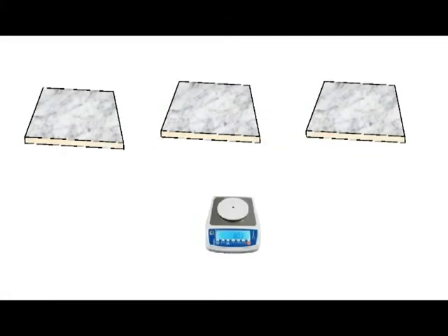Also a control of thicknesses is carried out, measuring in the most significant zones of the tile, and checking that no variation exists that would influence, among other things, the packaging process. Finally, a control of weight, or load of clay, is carried out, that like the variations of density or hardness, would also reverberate in calipers and deformations during the firing.